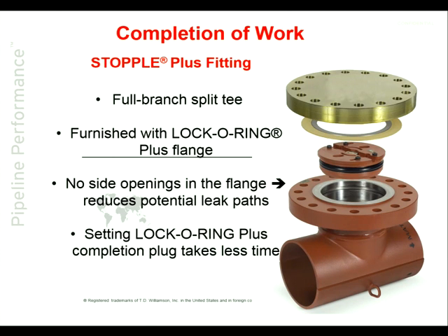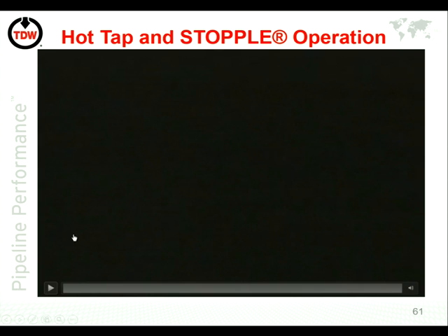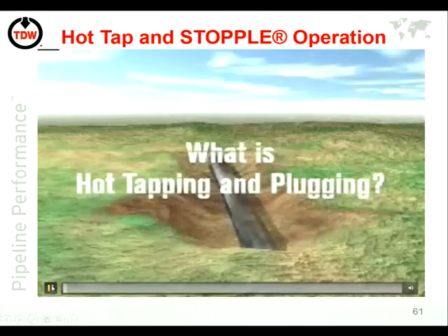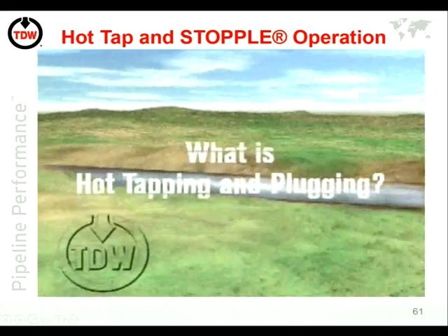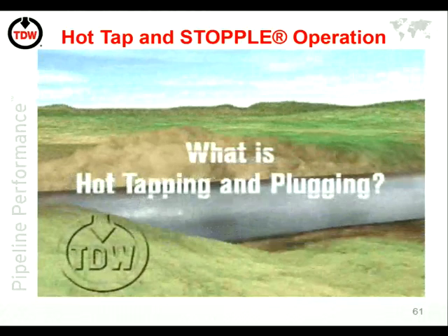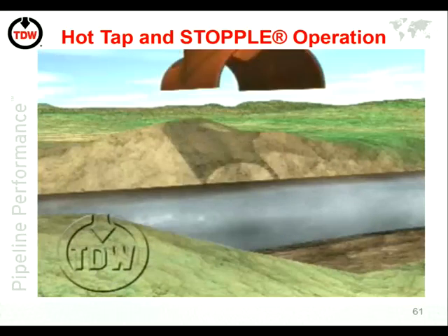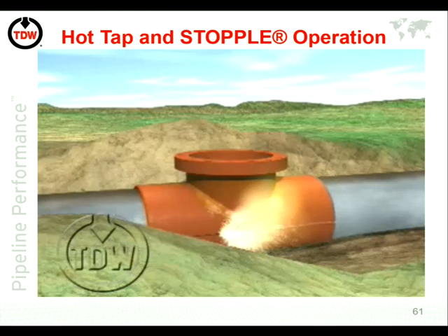I'll just run this. This is an actual tapping operation, and it's self-explanatory, and hopefully you can see. But please ask questions as I go along. This is summarising what we've just talked about. This is carrying out an operation on a pipeline. This is the welded fitting going on. We're going to do that 4 times, and then we fit 4 sandwich valves on top.